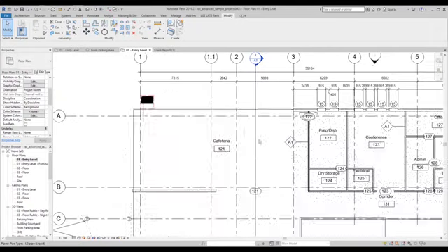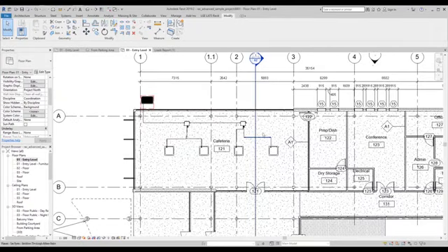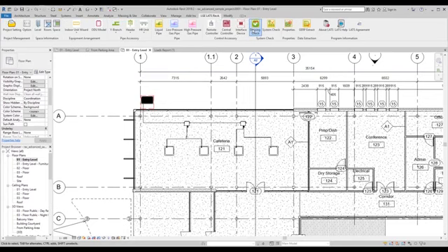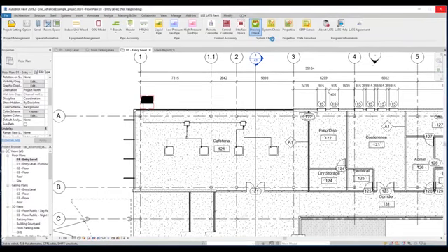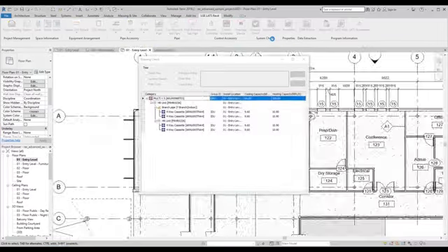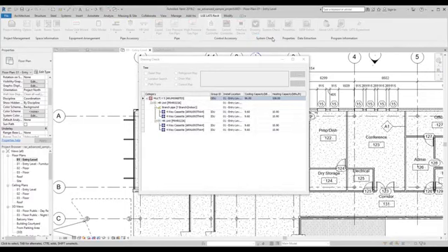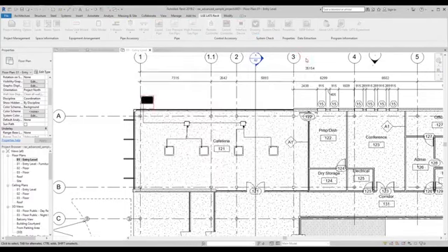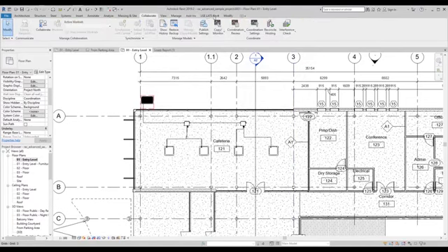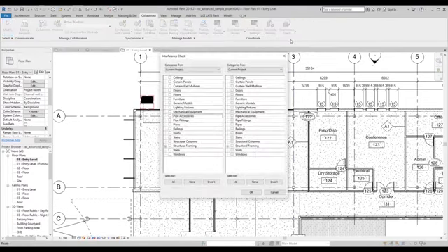The completed system may look something like this. You can always add control accessories after IDU placement. Click on Drawing to check for warnings regarding any improper pipe connections. Run an interference check to make sure the pipe connections are okay.